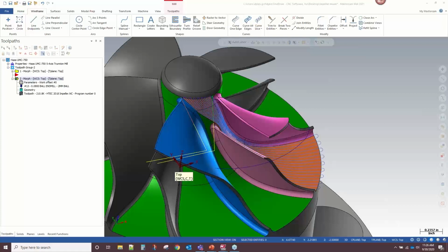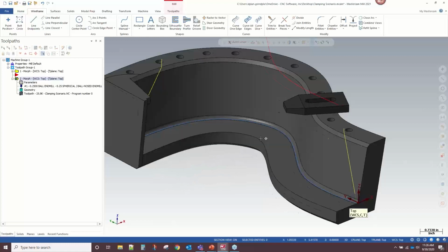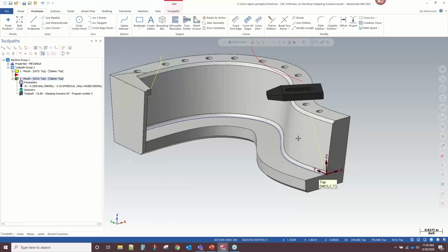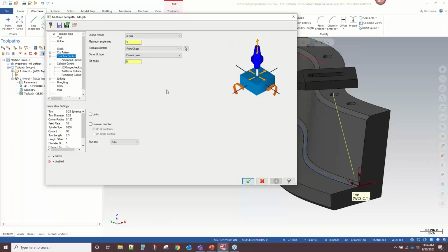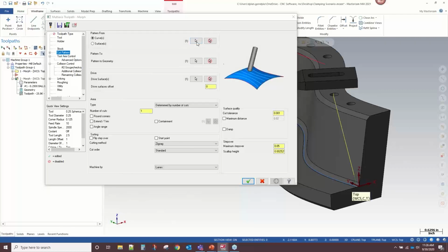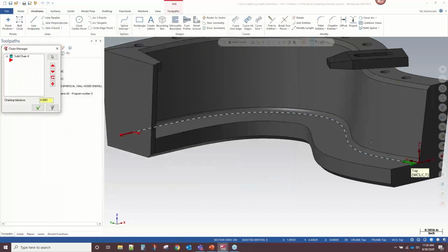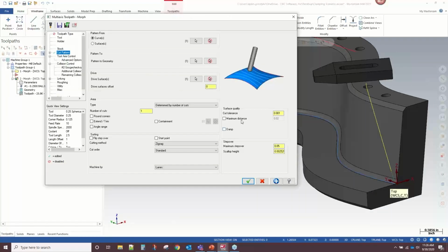So Jesse asks, how can you show us your drive geometry for the first morph example? So that would be this simple morph example I believe Jesse was asking about. And I was wondering if someone was going to ask about this, because this is kind of a nice trick in morph to do things like single sweep a fillet. So for this morph example, I'm patterning from the top of the fillet to the bottom of the fillet. And I've got the fillet as my drive geometry.